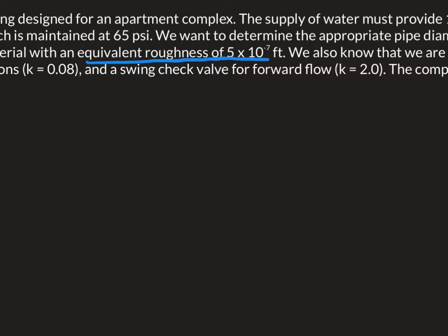And so the question is, is this the relative roughness, or is this that sand roughness factor? Is this that KS, or is this the relative roughness? And I left it in these words because I want you to think about kind of what I talked about earlier about different uses of the word epsilon. And what's important here is that this thing has a unit to it, feet, okay?